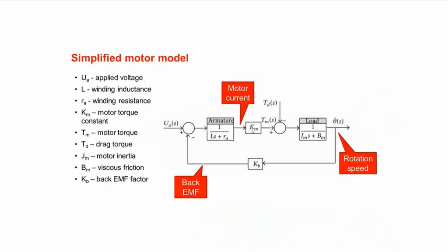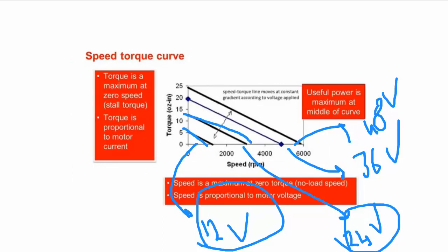But the two endpoints of the operation in the speed torque curve: at zero speed, we have maximum torque in a DC motor. If you are at zero speed, you have maximum torque. It's critical. So we get maximum torque when we are not moving at all, and if the load is not using up all the torque, that's where we get the most acceleration. So we accelerate, and as the speed increases, the torque comes down.